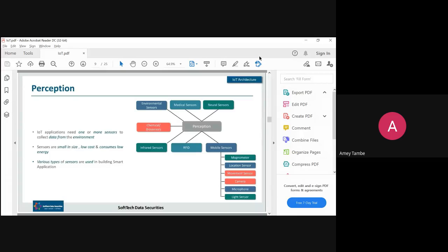If you look at that machine very closely, there are various sensors embedded. There is a conveyor belt which takes the bottle, and on the conveyor belt there is a weight sensor which senses the weight of that bottle. Accordingly, the product is filled in that bottle. Then there is a flow meter, or flow sensor. If it is a liquid product, a flow meter is installed at the nozzle point of that filler, which measures how much liquid is poured into the bottle. Once it reaches the number that is set, maybe 200 ml, 300 ml, 20 ml, 10 ml, 0.5 ml. If we are talking about medicines, then the quantity comes down to 10 ml, 0.5 ml, like that. Once that flow is detected, it automatically stops the fill.